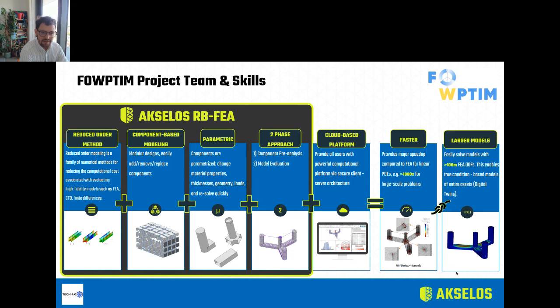One of these is component-based modeling, which makes it much faster to generate the reduced basis. If you're doing a reduced basis workflow, you start with an offline phase, which consists in generating the reduced basis based on a database of information that you have. But this is still difficult to generate if you're looking at the entire model. So we've broken up these models into repeatable components that are much faster to solve and then can just be duplicated to generate the full model.